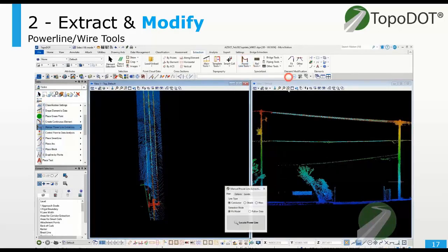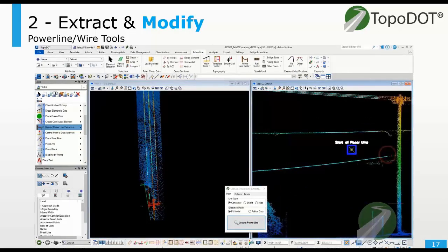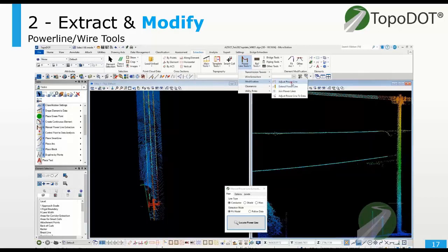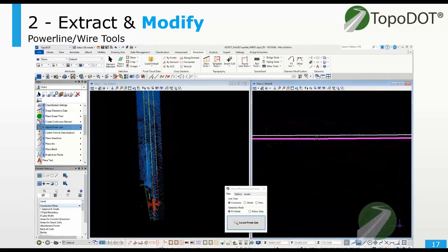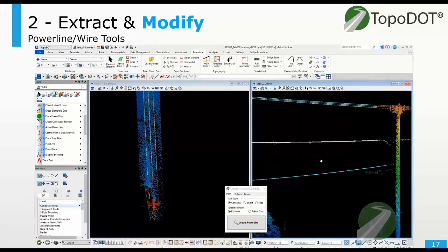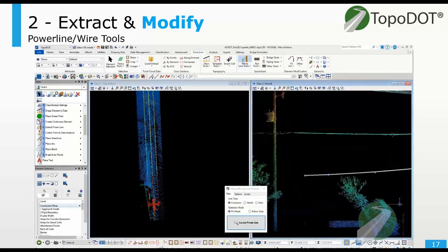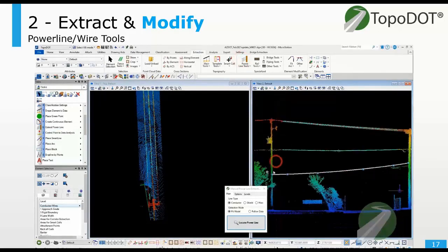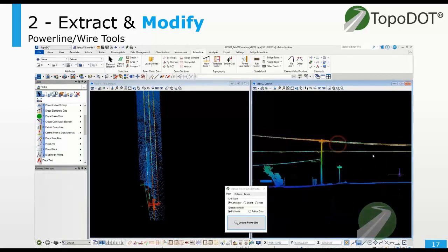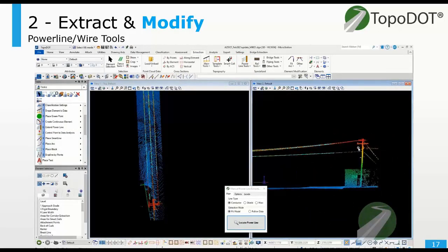So there's going to be some limitations on gathering everything, but we want to follow up with those companion tools associated with the power lines. So you got isolated single wires. And this is actually a pretty good example where there's not a lot of wire information on the other side of one of the lower wires here. So you can extend one end into the pole, and then you can extend the other side where there was no data. So if there's no data on that side of the span, it won't show up in the tool. So you can use that to help fill in those gaps.